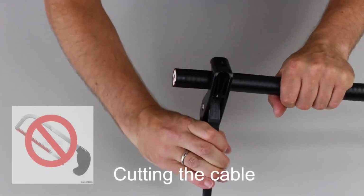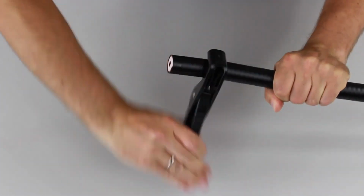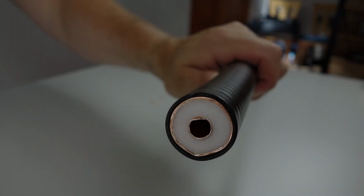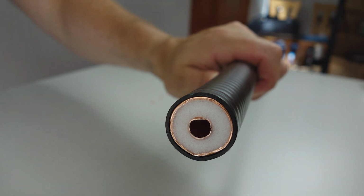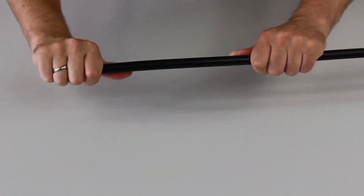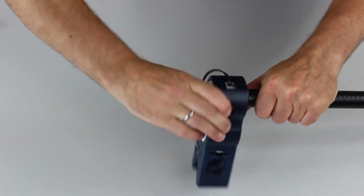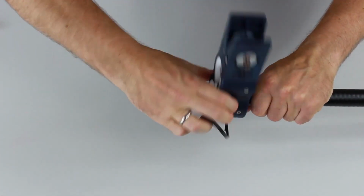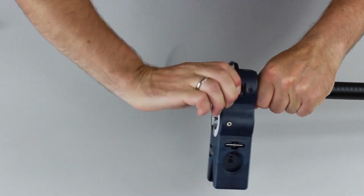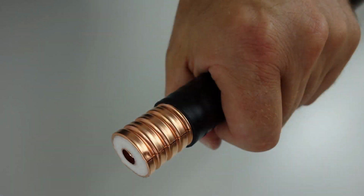Never use a saw to cut the cable. Move the cable cutter in a side-to-side motion and apply pressure to obtain a clean, smooth cut. Then straighten the cable to about 20 centimeters. Using the peeling tool on the Uni-Prep tool, peel off the sheath by working your way forward with a light feeding motion and turning the tool around the cable until you can see the end of the outer conductor protruding slightly. Clean off any removed sheath residues.